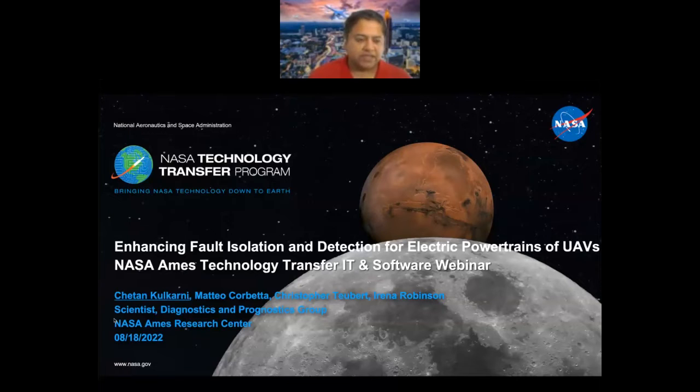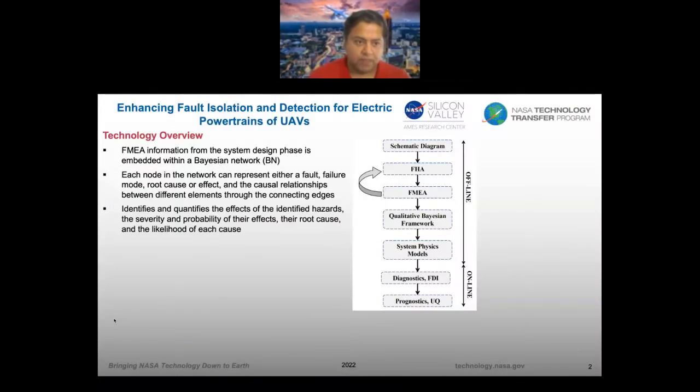So it leverages a combination of the FMEA, which is the failure mode and effect analysis, and a Bayesian network, which is trying to create a dependability structure within the diagnostics framework, mapping the failure events from the FMEA using a Bayesian network.